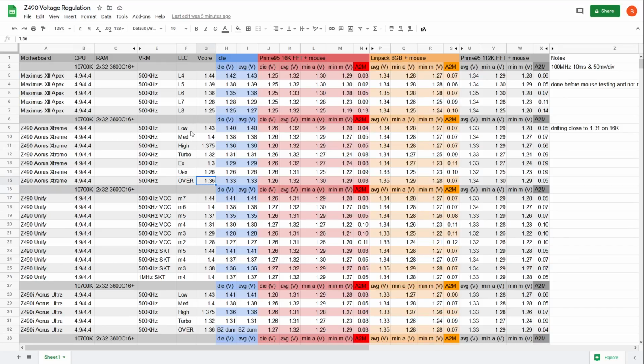But you might also want to check, there's a chance that in certain workloads override mode might have a disadvantage against static voltage with a manual LLC adjustment. I've just not run into that yet. Especially if you disable the power savings, I can't think of a single reason why override mode would be worse than static. If you have the power savings enabled, you might run into a weird scenario where the voltage doesn't come up quickly enough. You're idling at 0.9 volts, the workload starts, and you're still at 0.9 volts, then you're screwed. But if you disable the power savings, that should never be an issue because you'll always be at least at 1.33, and it'll pull you up as the current draw increases.